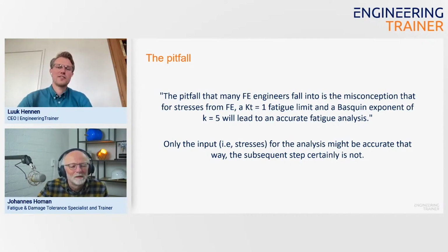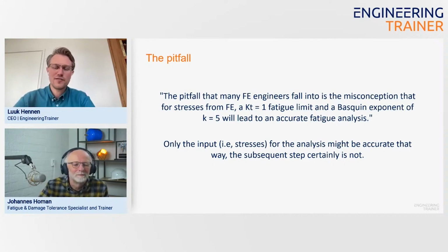Yeah, interesting. It's always tempting, when you're under pressure in engineering work, to use the code values. But this is a very interesting nuance. Yeah, certainly is. As I mentioned, very often the codes, the probability of failure of those SN curves is very low.